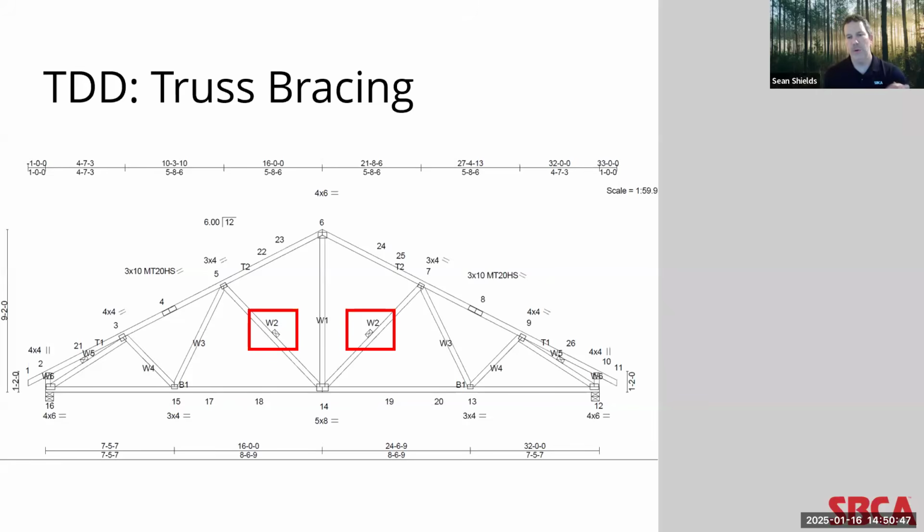Installing this bracing will allow the compression forces going through those two web members to be distributed between multiple adjacent trusses in the system. Again, this is sort of an interplay between the two-dimensional truss design drawing, the individual structural framing element that is a singular truss, and again, some of what may be required for the function within the overall roof system.